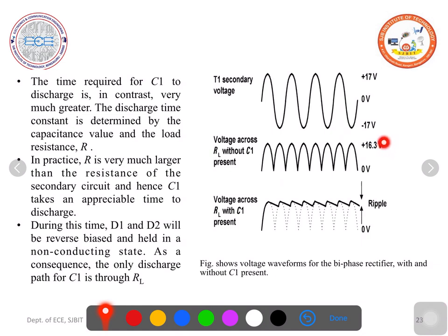across the diode. If you observe the frequency of the output voltage across the biphase rectifier, it is 100 Hz if the input frequency is 50 Hz. So how? So this is your time period, 1 by T is frequency, but here this is the time period after which it repeats itself. This is half. 1 by T is frequency. So here the frequency becomes 100 Hz, if the input frequency here is 50 Hz.